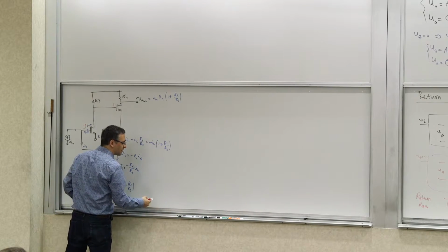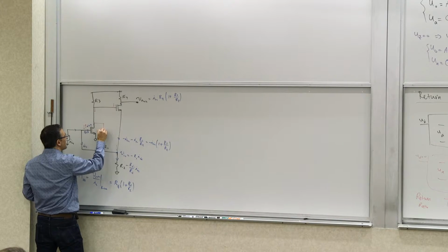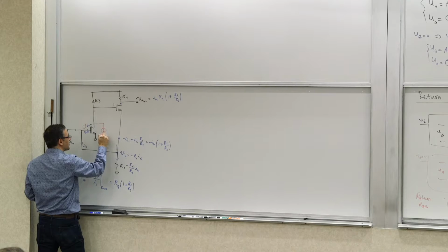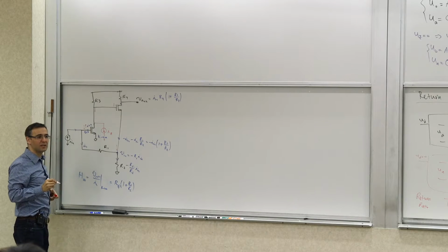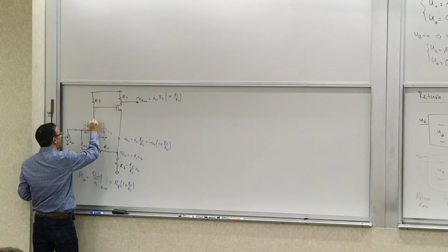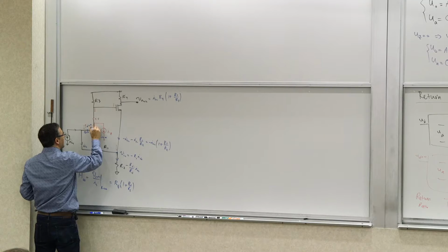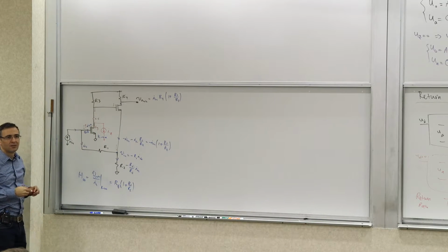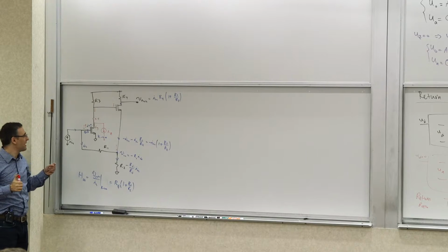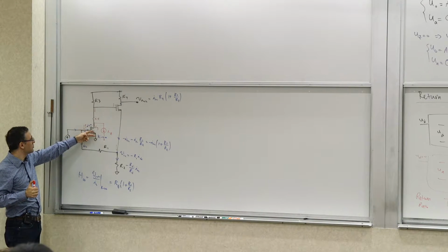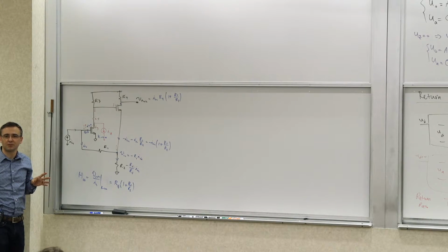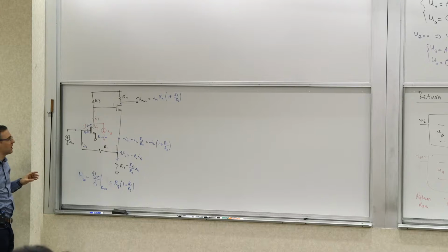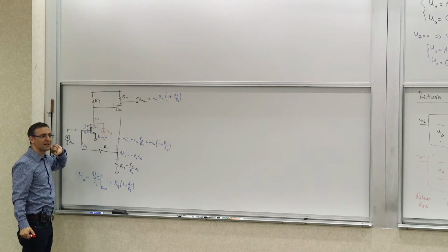The second thing you calculate is the return ratio, really. For return ratio, this is what we do. Because that's where our dependent current source is, I put a current source IZ here, which should never enter any equation. What it does, it produces an IX here and an IY there. The role of IZ is just to be able to generate a situation where IX and IY can be different. It just supplies the difference between those. That's all it does. So we have an IX here, so let's calculate the return ratio.